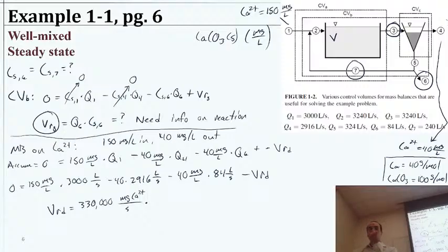Okay, so as you see from here, what I started to do to guide us along in figuring out this growth rate for the calcium carbonate in solution as solids is a mass balance on calcium ions. Like I mentioned, we go from 150 milligrams per liter to 40. I went ahead and brought in the molecular weights.